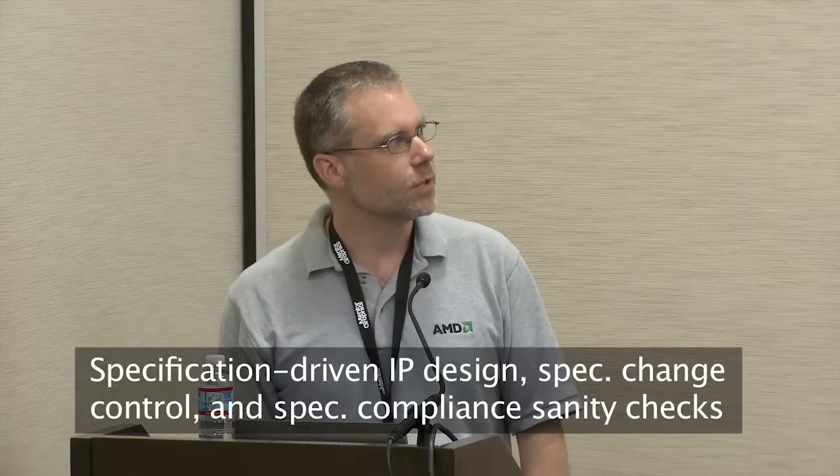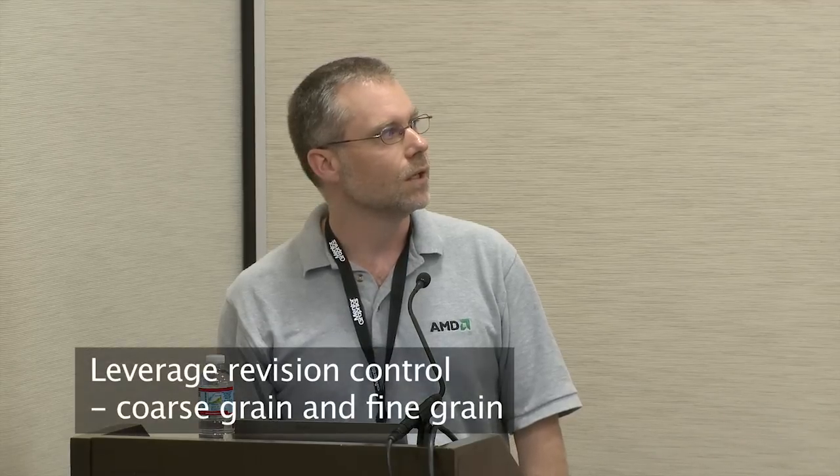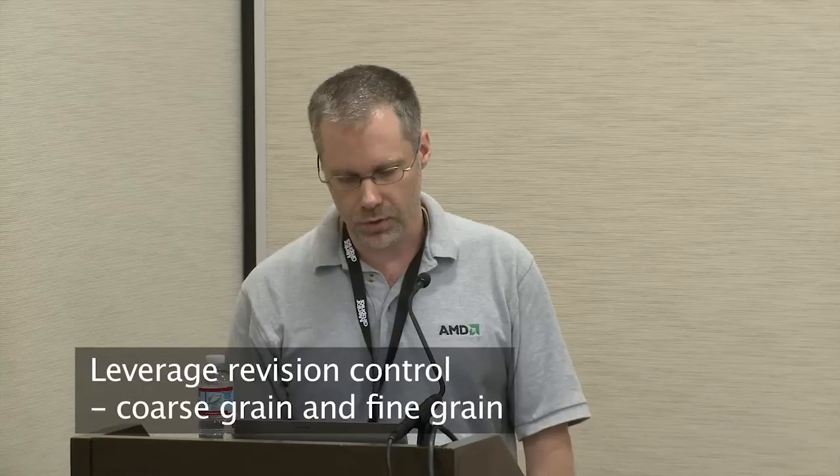In terms of best practices from a design and IP management system, essentially specification-driven IP design, change control, and that sort of thing. We need to ensure that we have the correct views ready for handoff, including all of the nitty-gritty things like the appropriate PVT lists, etc., that a given SoC product would need. Leveraging revision control. There are really 2 levels of revision control that we need to worry about. One is what I call coarse grain. Essentially, the handoff of large IP blocks to the various SoCs and making sure that the correct version of an IP block makes it to tape out.